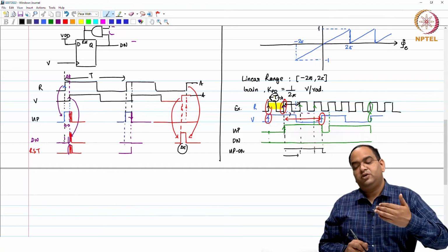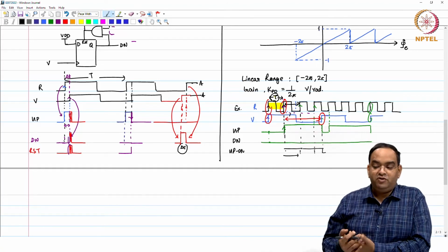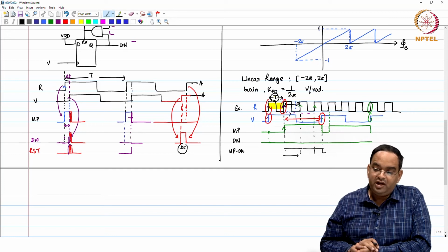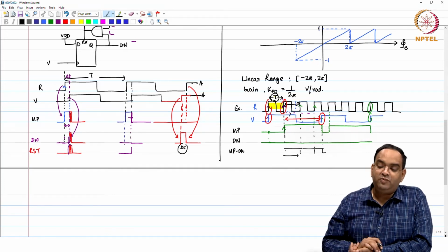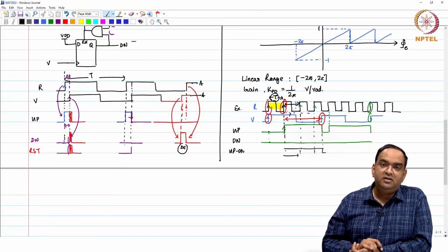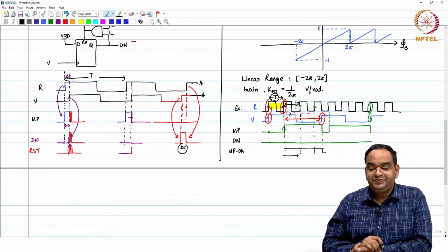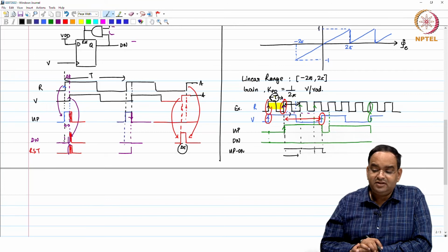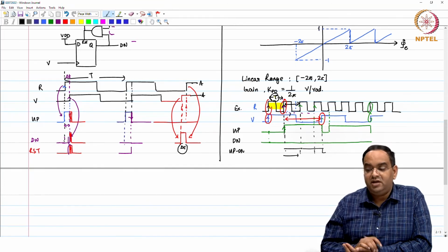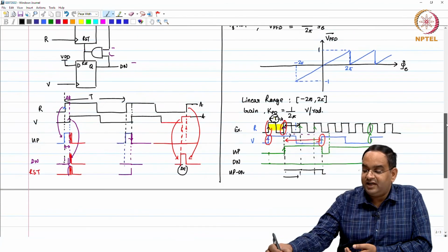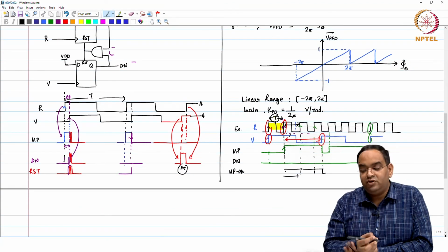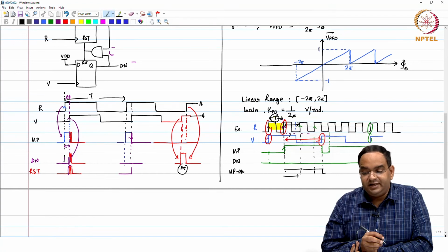So, your frequency error is large, your phase error is as shown here, your average value of PFD output is still limited between -1 to 1, depending on whether you have a positive frequency error or negative frequency error. In this particular case, your FR is larger than FV. Okay. So, you can say your reference accumulates phase faster than your V signal.